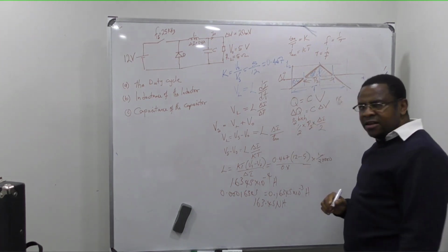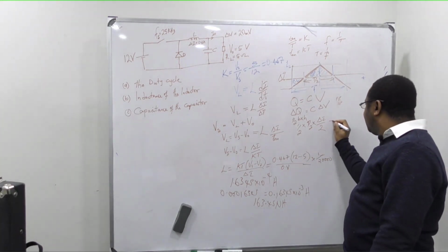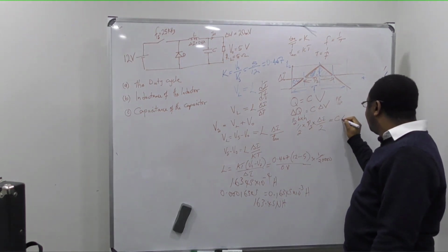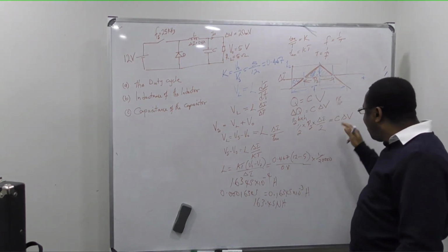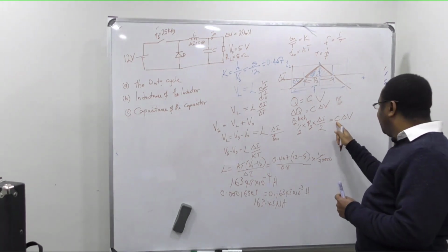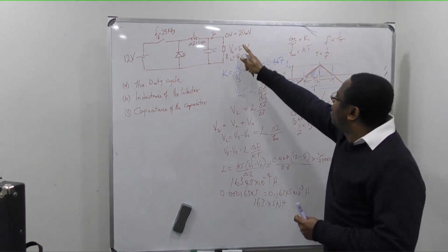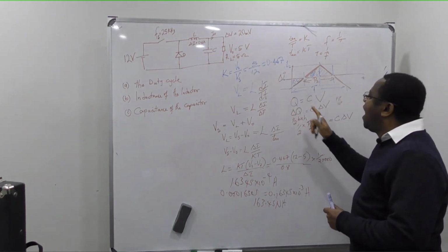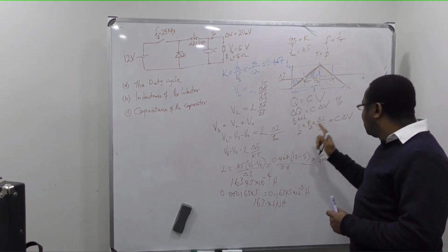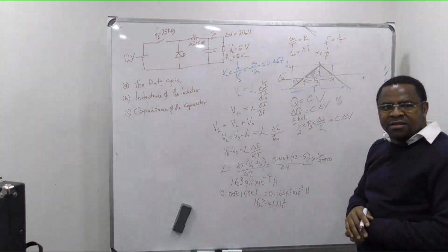So that is your height. And this is the quantity of electricity. And this is the same thing as C times delta V. See, now I have a nice equation that I can easily calculate C, because I know delta V is given to me somewhere, and I have delta I given to me somewhere. The period is also given, and this is constant, so we can easily calculate C.